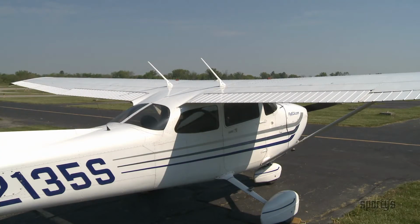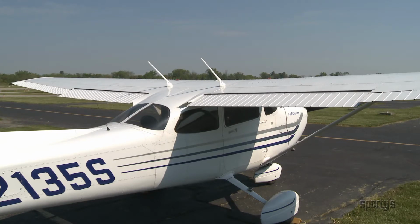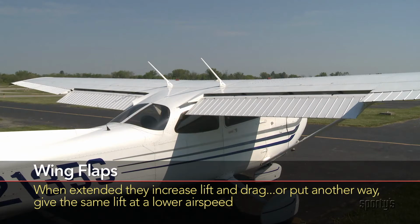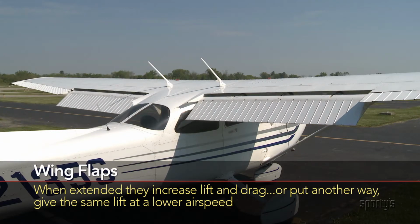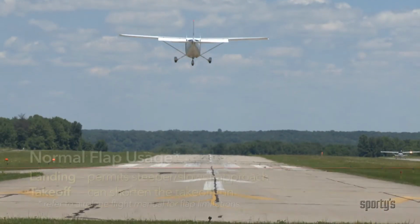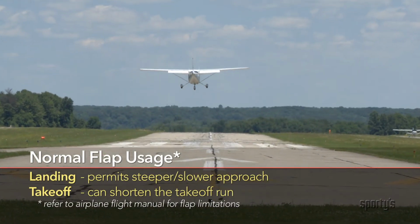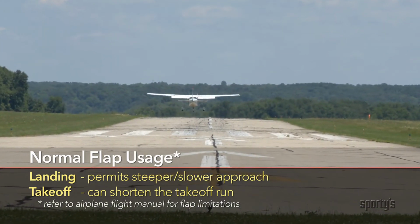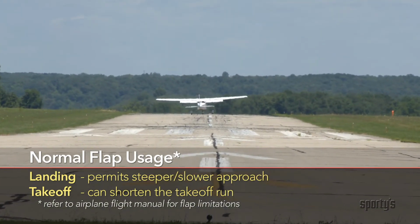The flaps are the panels on the trailing edge of the inboard parts of the wings. Unlike ailerons, both flaps are extended and retracted at the same time. Lowering the flaps changes the chord of the wing and increases both lift and drag. Extending the flaps allows the landing approach to be steeper and slower. In some situations, flaps are also used to shorten the takeoff run.